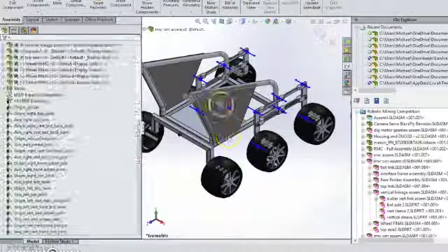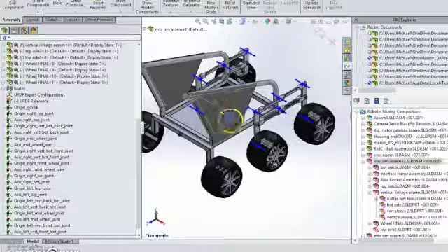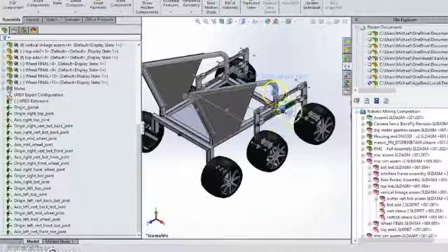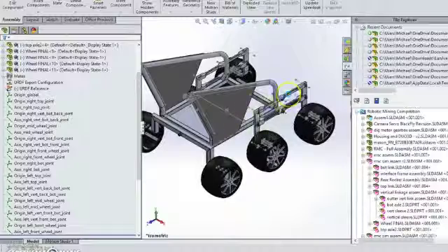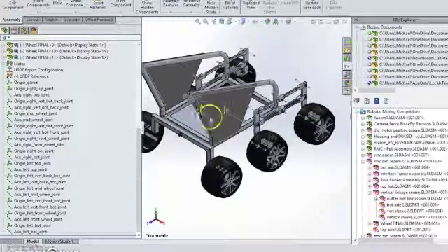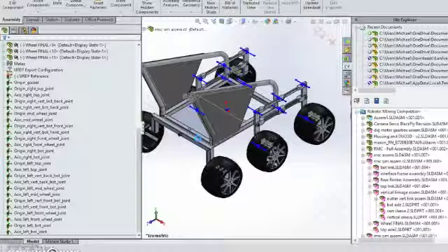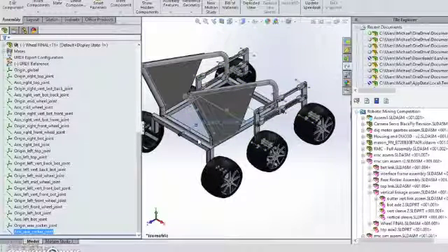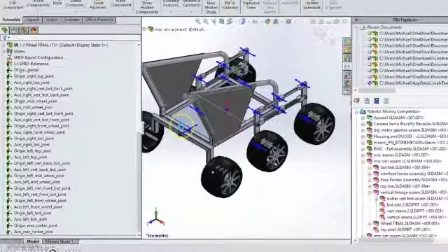So for the base link, the inertia is going to be based on its origin. But for these links, the inertias are going to be based on the axis of rotation and the part geometry. And that will be given directly from the CAD, which is one of the reasons that makes it quite valuable. So now we're at the rear transverse bogey.